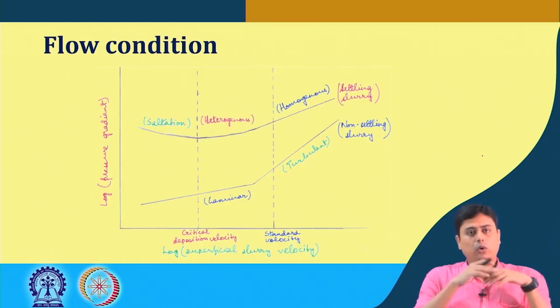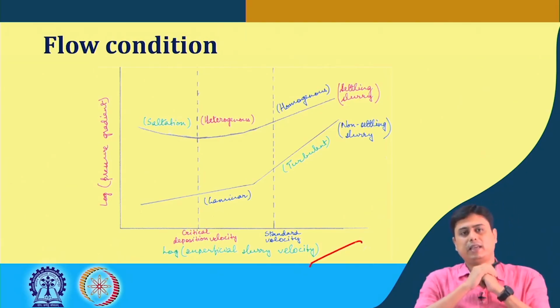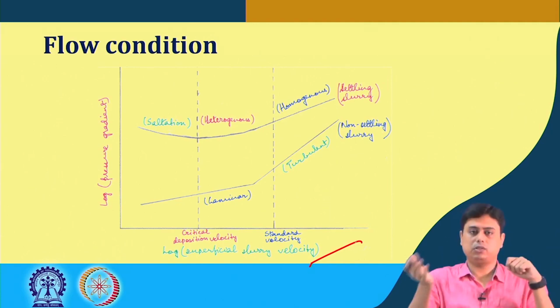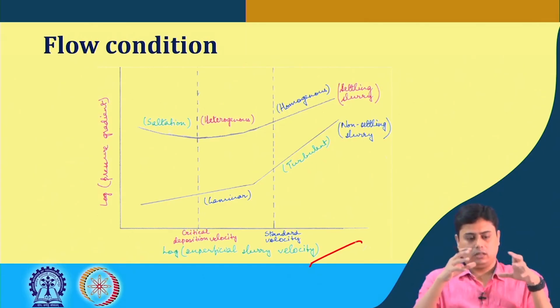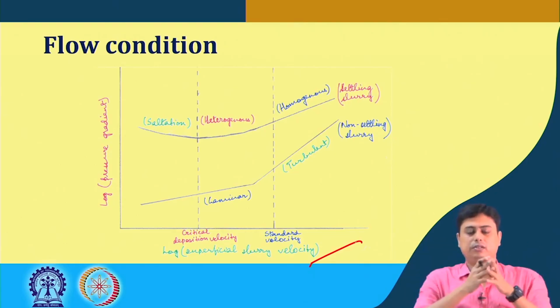If we look at the flow regime map, it would look something similar to the schematic shown here. This schematic is also important from the point of view of pressure drop calculation, because this is one of the prime concerns in moving the slurry from one place to another. This is the mechanical energy requirement that is dictated by the pressure drop when this transport is taking place.